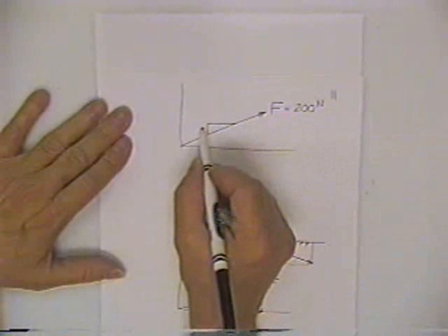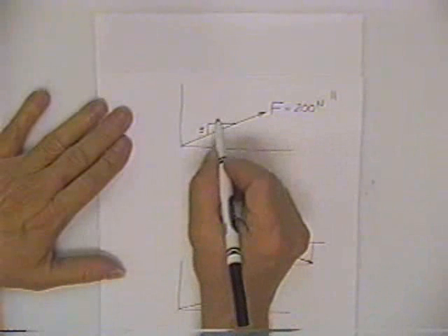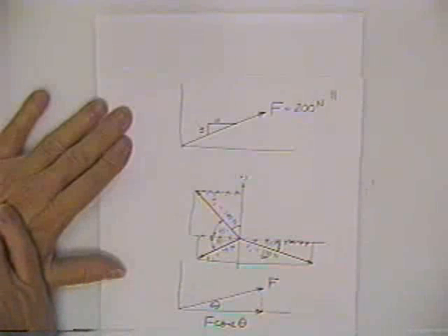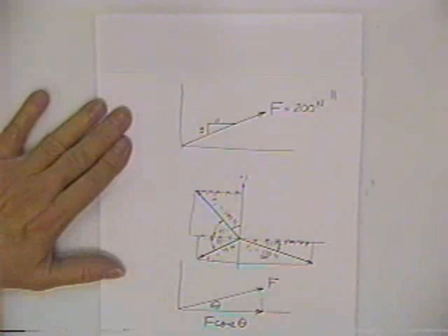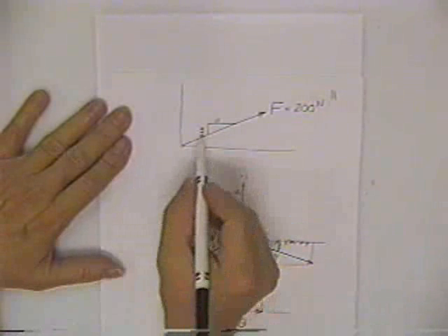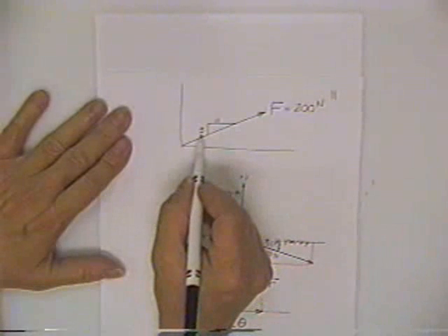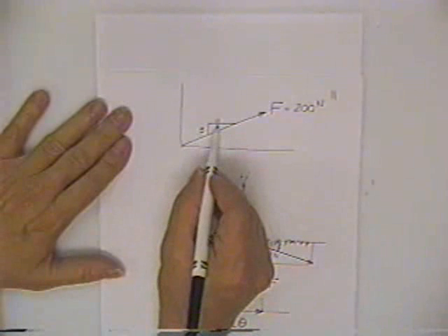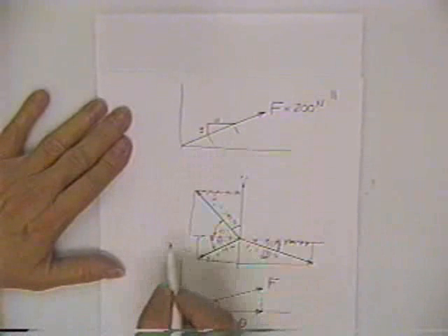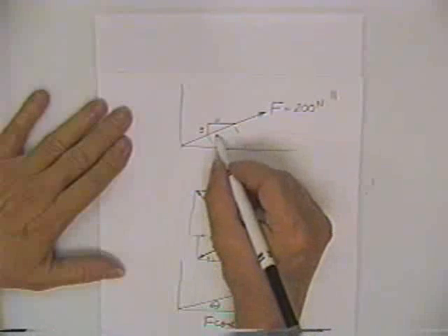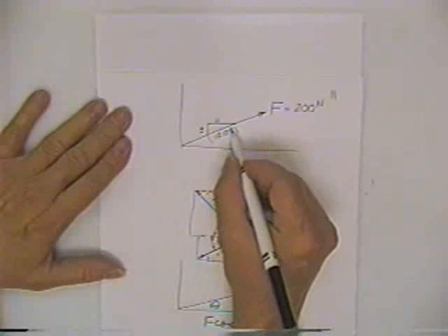Say this is a 5, this is an 11. In other words, the slope of that angle is rise of 5 and run is 11. Then I would take 5 squared plus 11 squared. Take a square root to find out how long this piece right here is. 12.08.